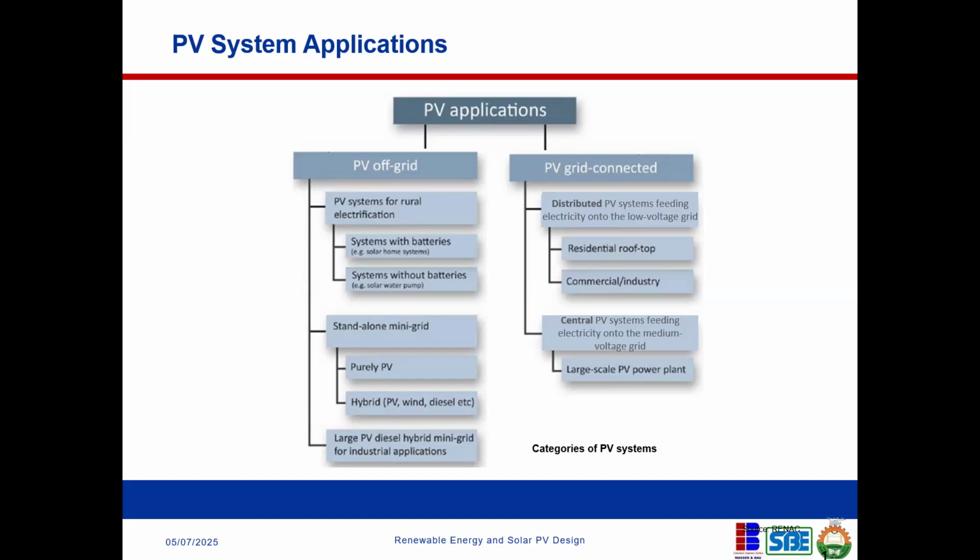Sometimes, to achieve high accuracy in the design, what we normally do is log that facility so we can see the grid availability over several months, if not up to a year, but sometimes it's difficult getting up to one year of data.